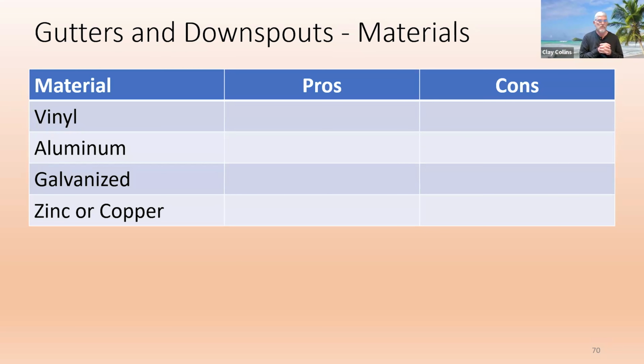Are gutters to be installed behind the drip edge flashing? There is no stipulation for that, but it only makes sense. Otherwise, you have water running over the drip edge behind the gutter where you're going to deteriorate your fascia because it's not drying out.